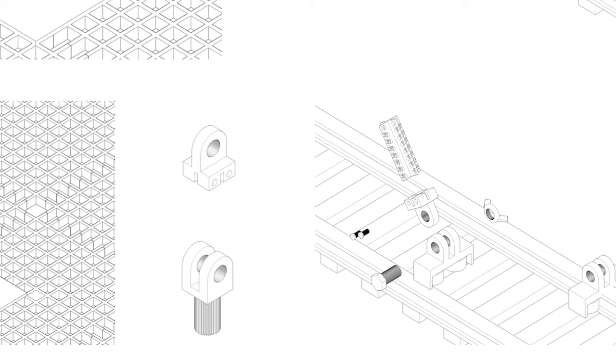The joint with the ground is connected by gears. This joint is easier to install, and it can also prevent the structure rod from rotating, enhancing its stability. In addition, there are rails in the site. We choose to use pulleys to fix the structure rods to the rails, which can achieve the effect of sliding.